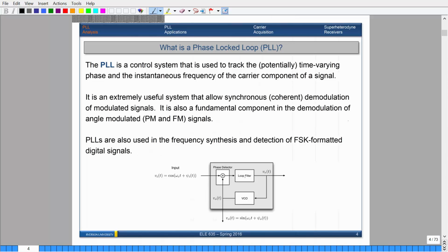So you can think of it as a control system where the input signal or the reference is your carrier wave, and the output will be, so inside here is what is known as a voltage controlled oscillator. So it's basically just a miniature, you can think of that as a carrier, quote unquote, and then the objective is, given an input sinusoid that you put in, the voltage-controlled oscillator will match the frequency that's coming in and give you an output frequency that matches the input. So think about it in terms like as a reference signal, which is your carrier. The output will be an additional cosine that matches that particular frequency.